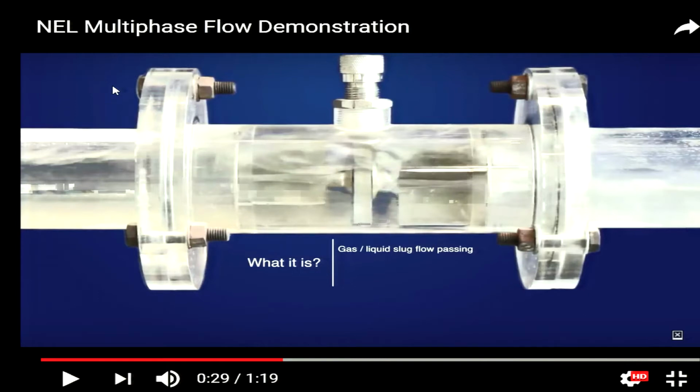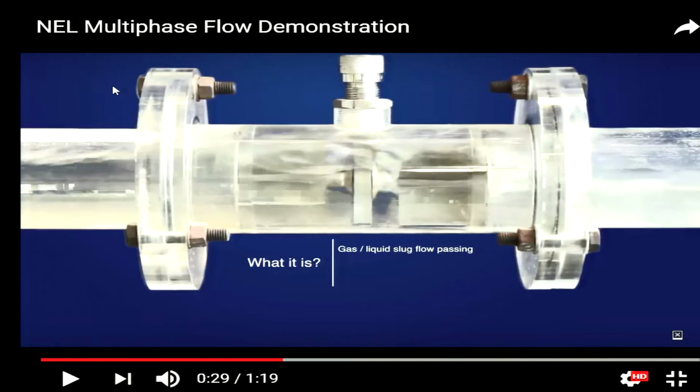Okay, so here they show that the conventional way that people use is a turbine flow meter. But the problem is, if you use a turbine, I mean that's a common standard, but even that creates complication, because the moment you put a turbine flow meter, it messes up the whole flow regime. So the act of measurement starts affecting your system. Okay. So, just look at it.